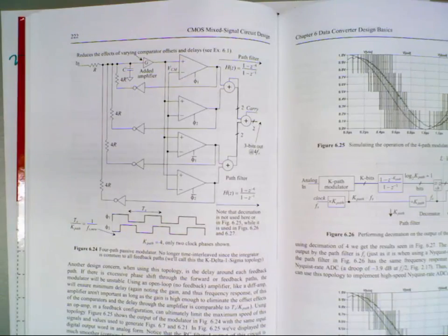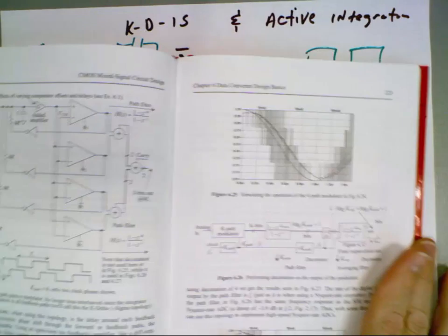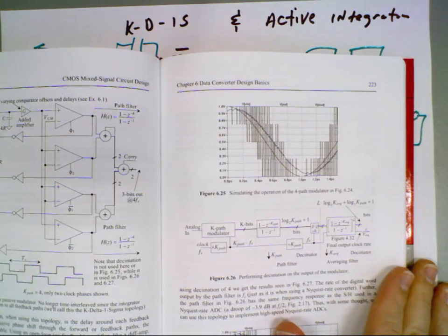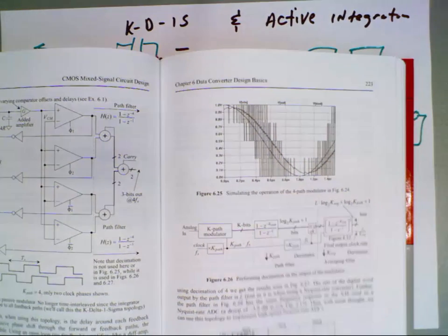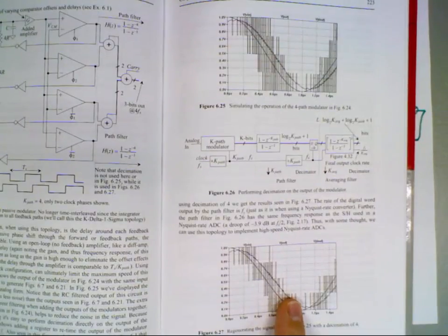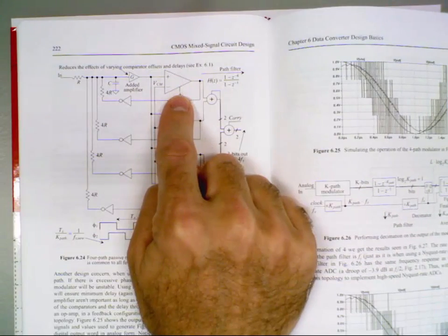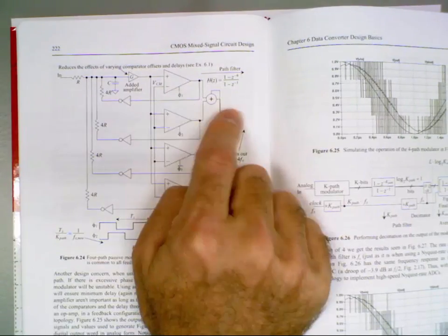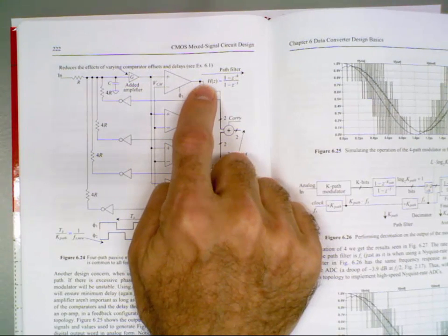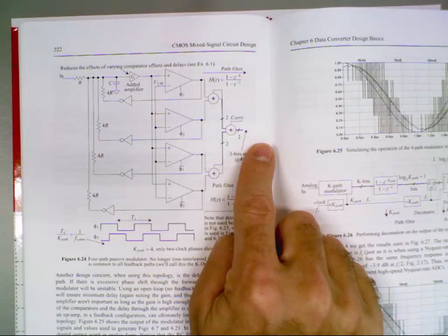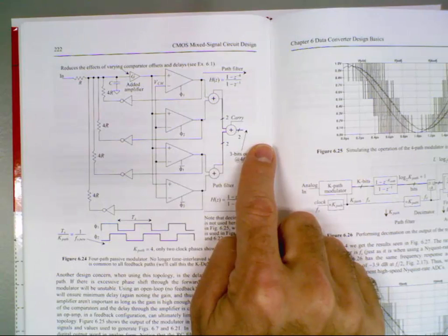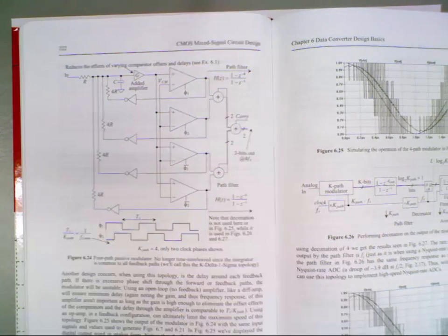Now, a little caveat here: when you do these sims, everything looks great. You do the MATLAB and pull out the results and everything matches theory perfectly, and the reason is because you're using ideal components. When you start to use non-ideal components, meaning the comparator doesn't make an instantaneous decision, you start to get reductions in signal to noise ratio, and you have to do things like resynchronize the bits out here so that they come out without metastability problems. Okay, we'll cover this more later.